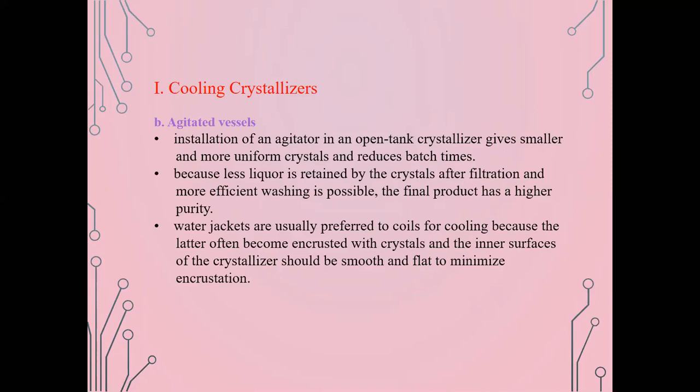Now, water jackets are usually preferred to coils for cooling because the latter often become encrusted with crystals, and the inner surfaces of the crystallizer should be smooth and flat to minimize incrustations. So we don't want the stirrer or the coil of the cooling medium to be encrusted with crystals, nor the surfaces to be encrusted as well.